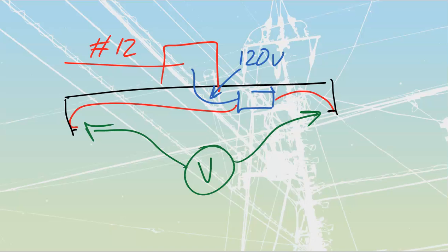They do go back a little bit up to occupancy sensors, daylight harvesting, and load shedding. Yes, we can switch stuff off. They do say that we can dim. We can't really dim with most fluorescents, so we're going to skip past that. That should never have been written in the module, but most fluorescents are not dimmer compatible. You burn them out. We will load shed at times if we hit those peak limits.